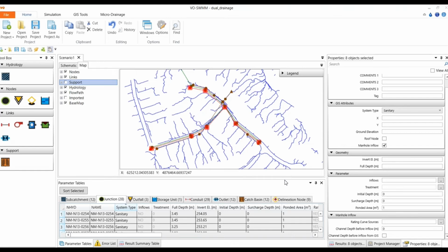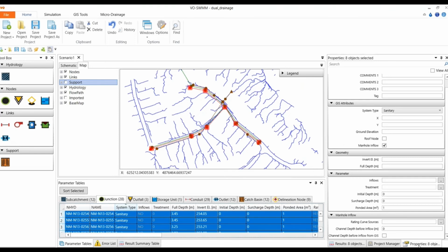All these values when we're modeling manhole analysis are provided by the clients, or we can go and get or calculate the data, but most of the time the clients provide it. So you can either manually input the data, select each of these and then go here and enter, let's say, 1.2 or whatnot. Or you can create a CSV file, especially if you're having a big project with a lot of manholes, where it may not make sense to do it manually.